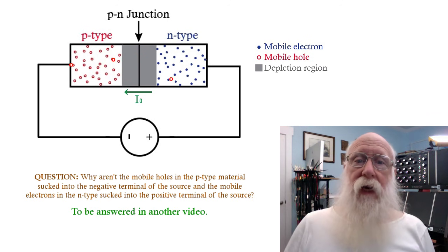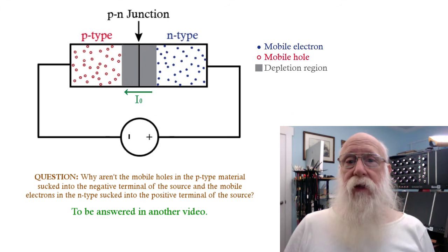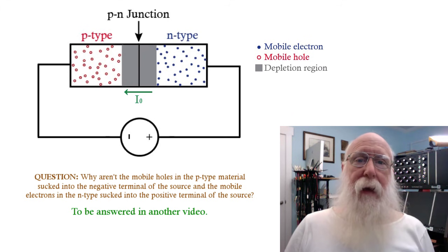Now, by the way, you can make a similar statement about the N-type and holes being freed up, but the situation is quite analogous. Now, interestingly, this reverse saturation current is almost independent of the actual external voltage generating that reverse bias, except at extremely low voltages, or unless the voltage gets large enough for something a little more interesting to happen.